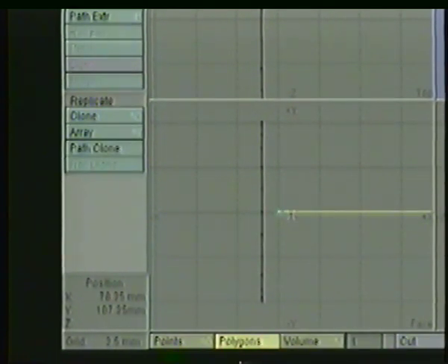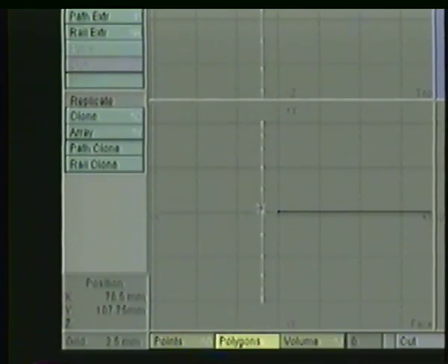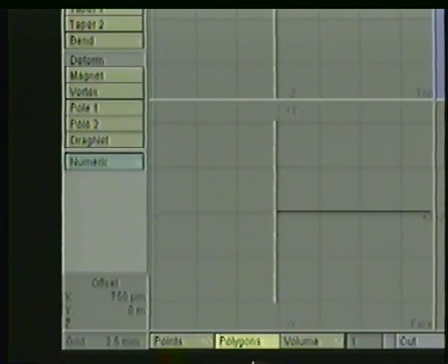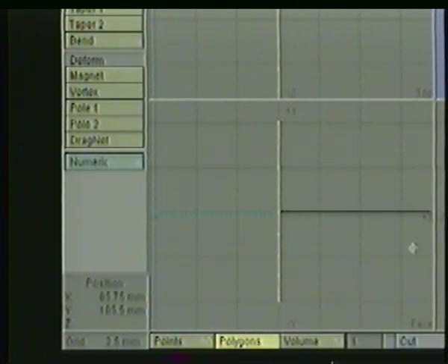If it wasn't the starting point, the extrusion would try to happen in the opposite direction. If you have problems where your extrusion is shooting off into space, check to make sure that your rail is facing the right direction. I'm going to swap layers with the apostrophe key again, and once again select the polygon, and go to Modify, use the Move tool, and drag this over so it's right at the end of my spline, right at the end of the rail.